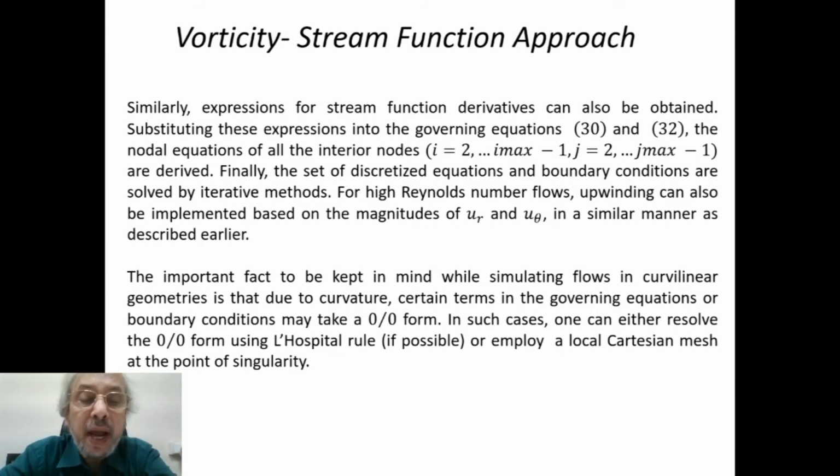The important fact to be kept in mind while simulating flows in curvilinear geometries is to always remember that because of curvature, this 1 by r term, certain terms in the governing equations or boundary conditions may take 0 by 0 form.